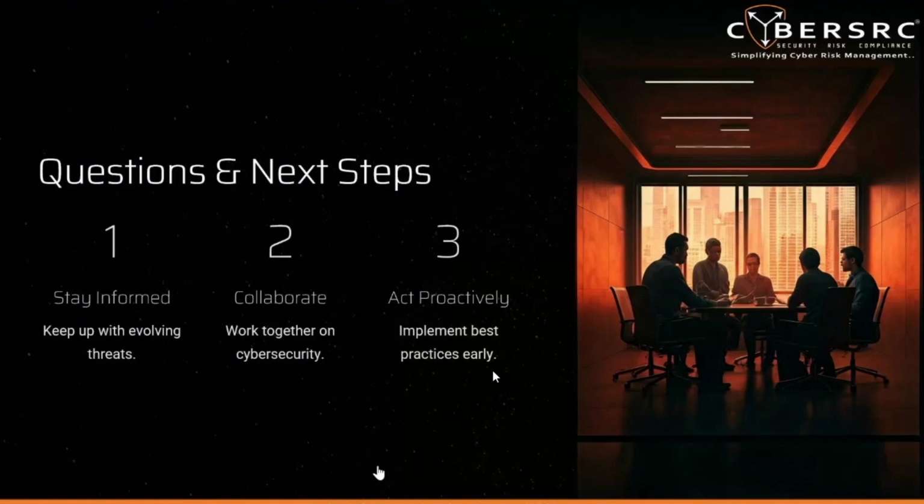How do we ensure OT plants are secured enough when they have legacy systems? So what can we do in this case? For legacy systems, as I told you before, proper network segmentation using firewalls with security best practice configurations. We can also enable IDS and SIEM solutions to ensure proper monitoring of the network, employ proper segmentation and a DMZ between the enterprise layer and the OT layer, and also prevent unauthorized remote access to the legacy systems.